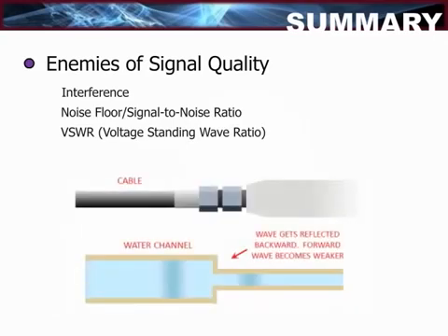The voltage standing wave ratio is a property of antennas that need to be considered in order to ensure the outgoing signal leaves the transmitting system smoothly. If the VSWR is too high, this will both weaken the transmitted signal and cause reflections back into the transmitter, which can potentially cause damage.